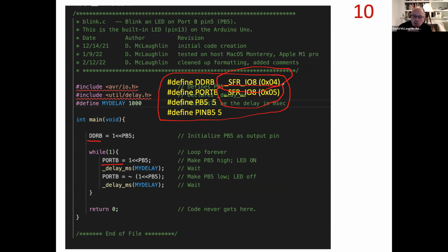We've used these before in our programs. It makes it really convenient to program with these because we don't have to worry about the actual numbers, the hex or memory address locations. That gets taken care of for us. So that's the purpose of this include statement. It gives definition to these things, and we had to tell the compiler which processor we want. This command will then pull in the right header file with all these definitions, matching them up to the memory locations. Okay, so that's what's going on.